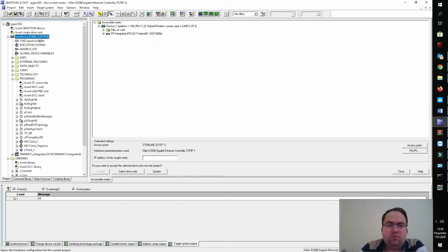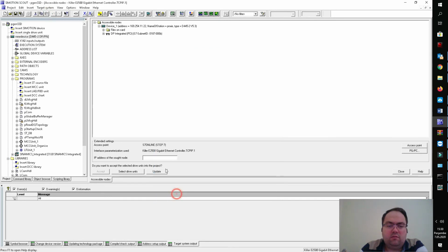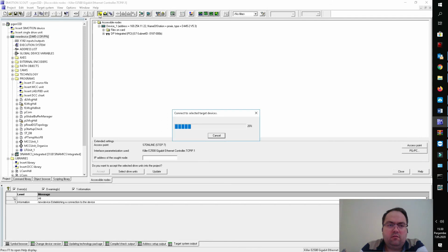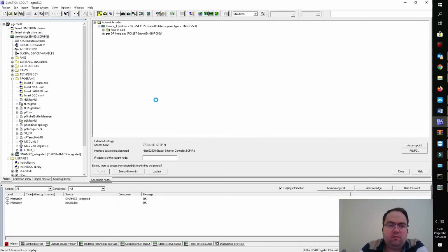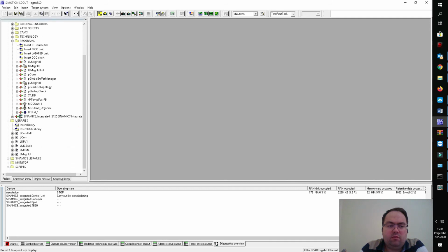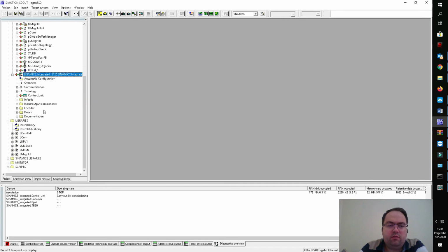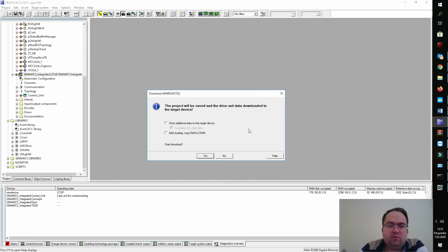Let's select the target devices, CPU and SINAMICS. When I hit the connect online button, now I'm online to my CPU. You see here the difference between online and offline partner. So let's select and download the SINAMICS side first.